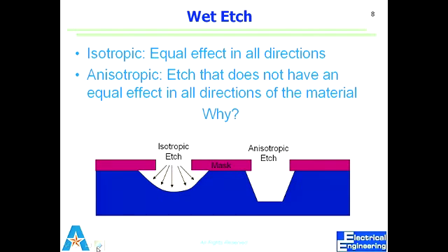So this is a close approximation: if there's single crystalline silicon with 100 in this direction, then this is 111, and this is just a slice. Essentially, this would be an inverted pyramid, right? You know pyramid? There are 4 triangles, right? And there is the center.